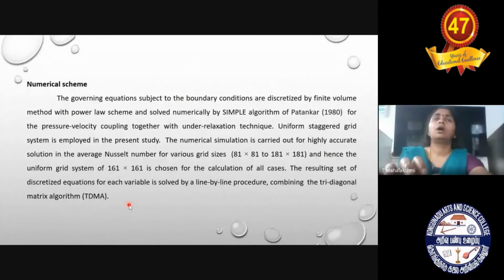Either we can move with simple Simpson's 1/3 rule, or Simpson's 3/8 rule, Runge-Kutta second order, third order, fourth order, whatever we feel to consider, in the heat transfer calculation at the last stage of the entire numerical simulation. I have considered Simpson's 1/3 rule in the heat transfer analysis here.